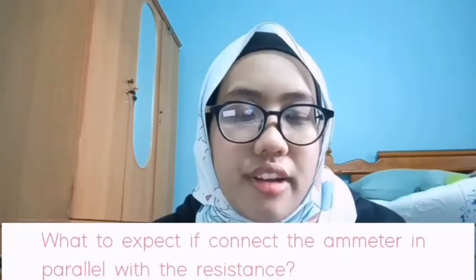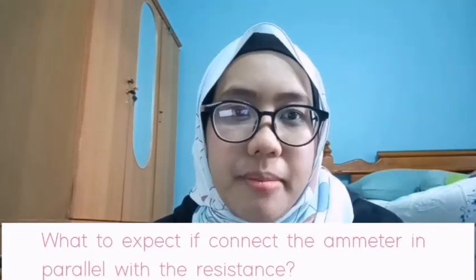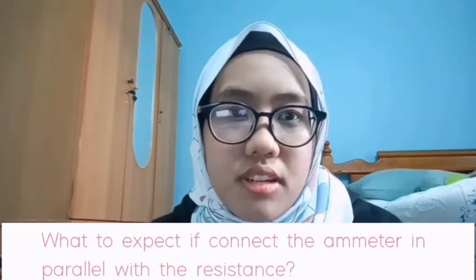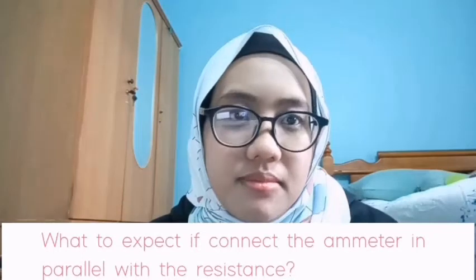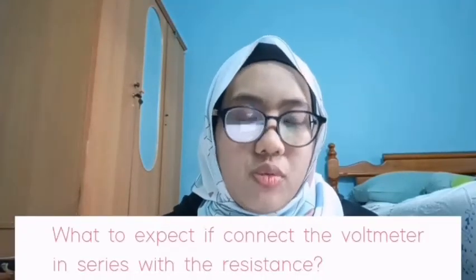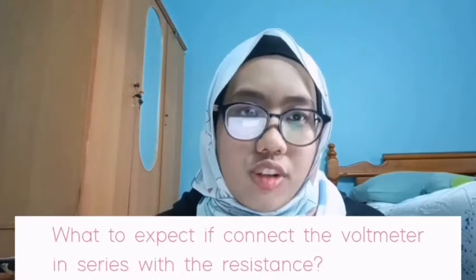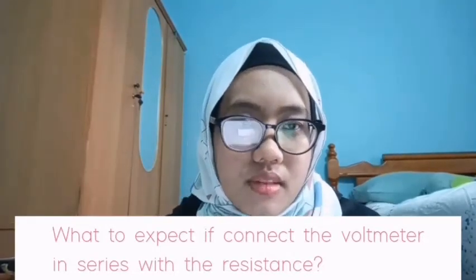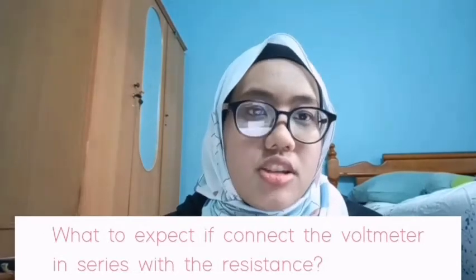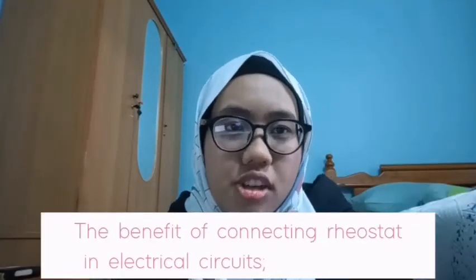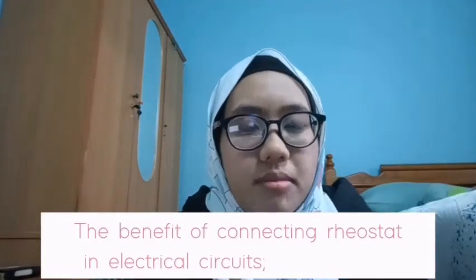All the available current will flow through the ammeter and damage it, or it won't give any typical reading for the circuit being tested. A high impedance of the voltmeter will result in a significant voltage drop in that part of the circuit, so the value shown is not the typical value of that part of the circuit. A rheostat can change the resistance without interrupting the circuit.